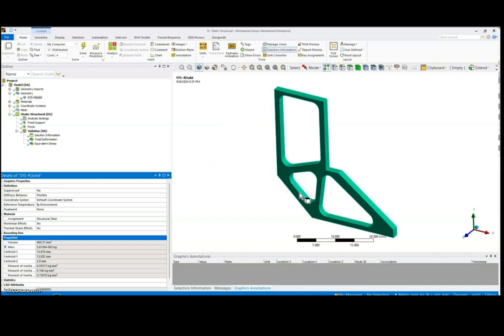This is the entire flow: from topology optimization to find the best optimum shape, then use SpaceClaim to build a model based on the topology optimized model. Then from there, we perform further parametric optimization to minimize the weight, at the same time ensuring it fulfills the design constraint of less than 0.3 mm total deformation. Then this is the entire full flow of procedures. Thank you.